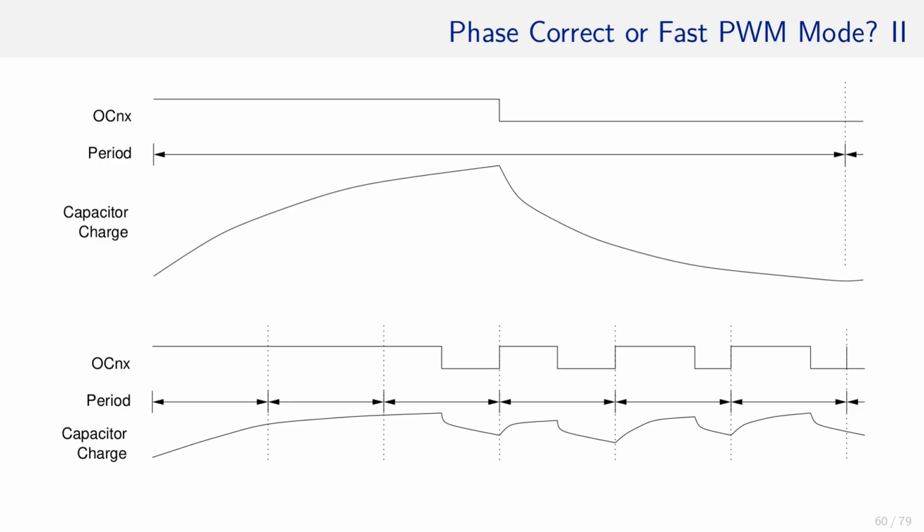The problem is that the output at the pin is still a nearly rectangular waveform. So either the pin has full voltage or none. Many times PWM is used to create intermediate voltages between 0 and the so-called supply voltage, or VCC.